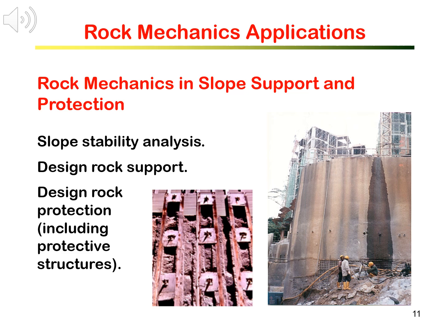Rock reinforcements are to enhance and increase the rock mass strength, so the slope can become stable and safe. Rock support is to provide additional structure to help the rock slope carry the loads. We will learn later, for example, how to use the rock mass rating, the RMR system, to analyze the slope stability and to design the slope support.